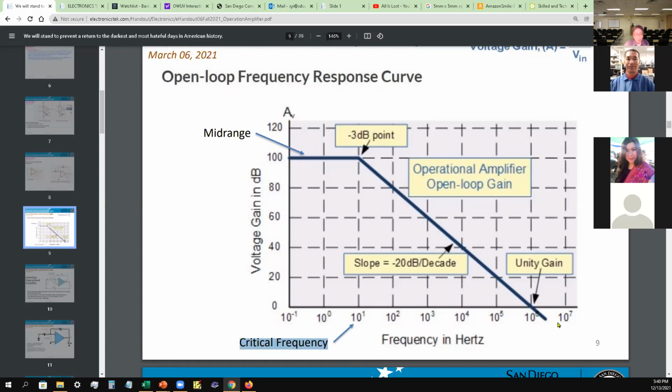You want more frequency. In order to get more frequency, you have to reduce the gain. You see that? This is the gain at 100,000. At 80,000, the bandwidth goes up to 100 hertz, and they keep reducing the gain. Okay? So if you want more bandwidth, then you have to reduce the gain. That's the only question.